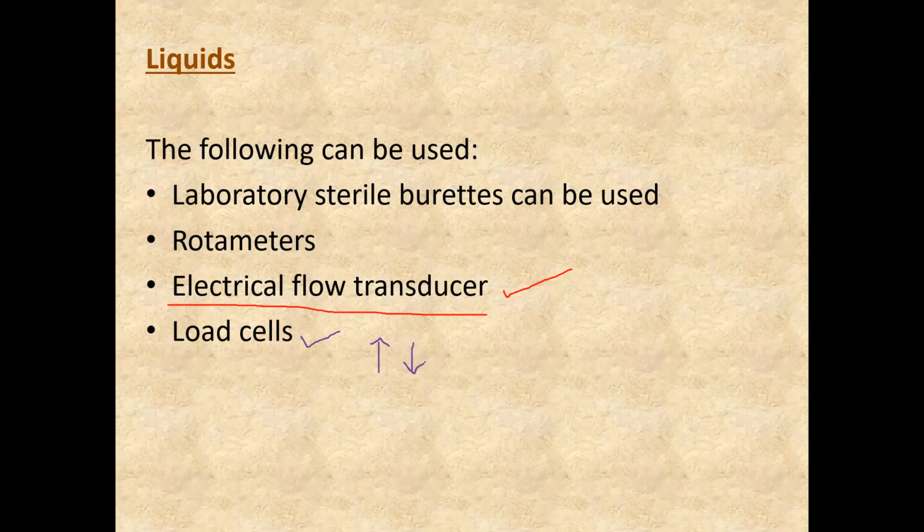You would say we wanted to find out the flow rate of liquids. Load cells are not telling us the flow rate. In fact, they're just telling us the increase and decrease in the weight of that vessel at regular time intervals. Yes, provided you know the specific gravity of the liquid, you can estimate the flow rate fairly accurately in different vessels and pipelines.